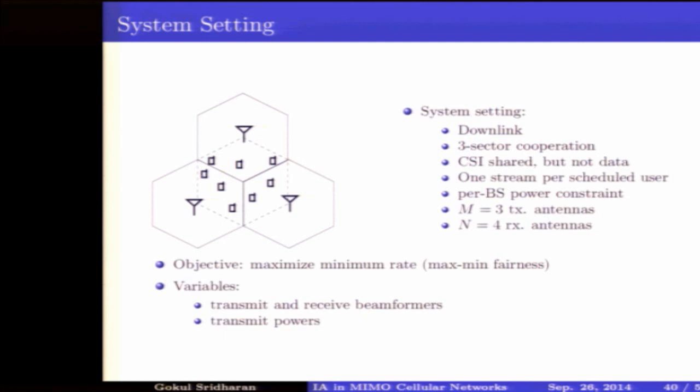So if you don't cancel that interference, you're basically looking at the SINR, which would just be a few dBs. But the moment you remove those 2 interferers, you get maybe 20, 25 dB. And you can only remove these 2 interferers completely if you restrict yourself to scheduling for the parameters that I've chosen, 2 users per cell.